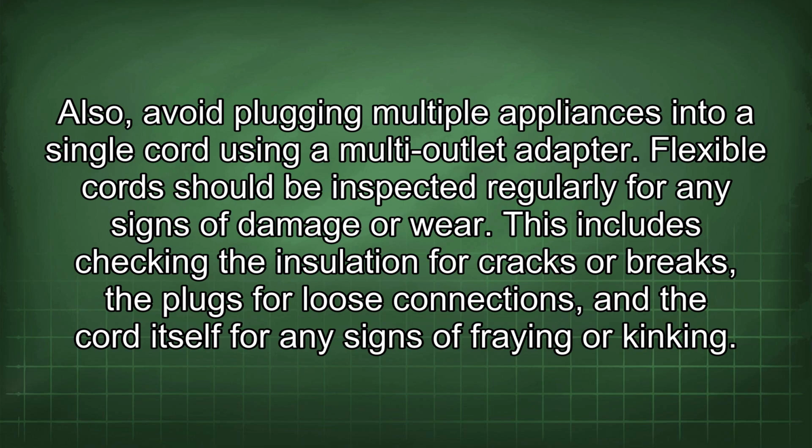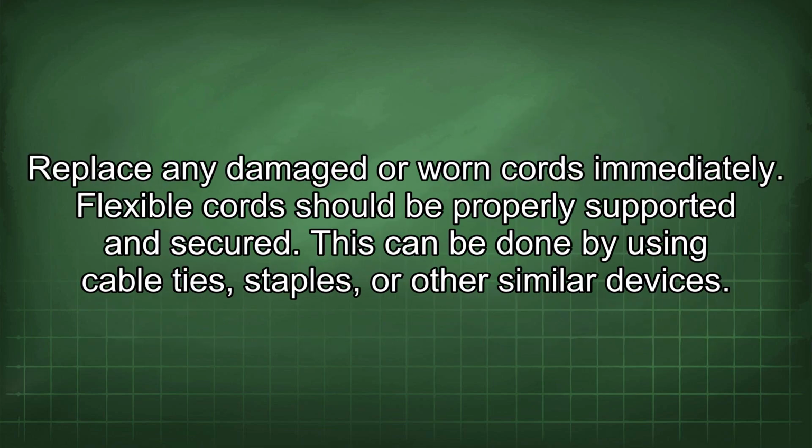Flexible cords should be inspected regularly for any signs of damage or wear. This includes checking the insulation for cracks or breaks, the plugs for loose connections, and the cord itself for any signs of fraying or kinking. Replace any damaged or worn cords immediately.